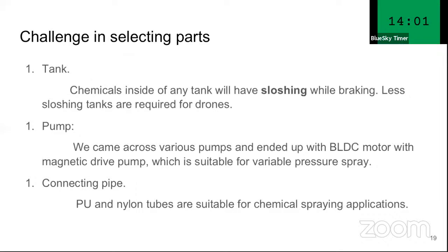That means we take the drone and its GPS and walk around the plot of land that we have to spray, and then we inform the drone's coordinates that this is the region within which we will have to spray. And we can now do an autopilot, and the autopilot will essentially do this rastering within this region. And that is what is called waypoint navigation.